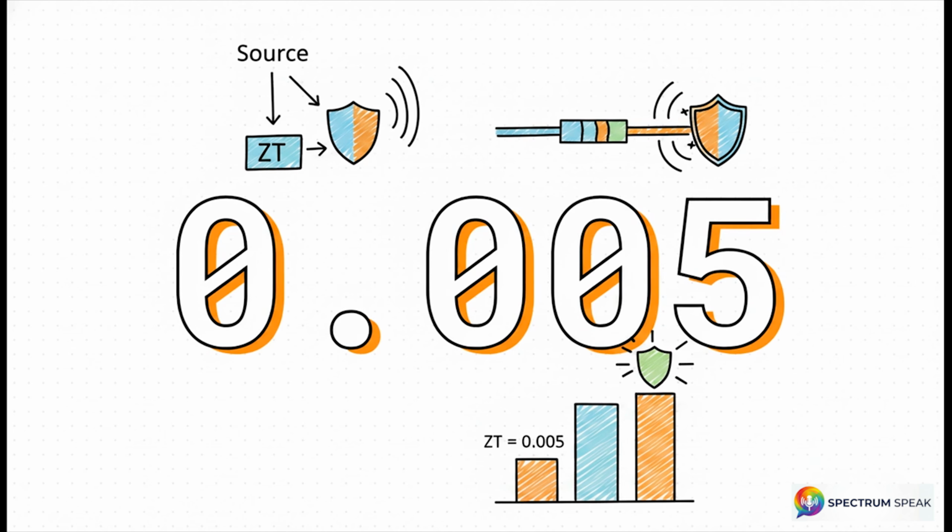And remember, because transfer impedance is sitting down in the denominator of our shielding effectiveness logarithmic formula, this proves mathematically that if we were to drop that Z sub t down even further to, say, 0.001 ohms per meter, our shielding effectiveness would absolutely skyrocket. A smaller transfer impedance fundamentally, unequivocally guarantees a much more effective shield.